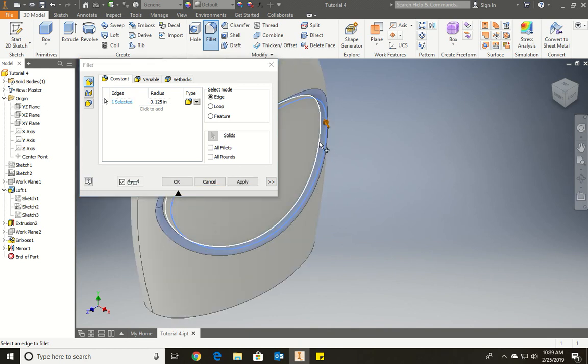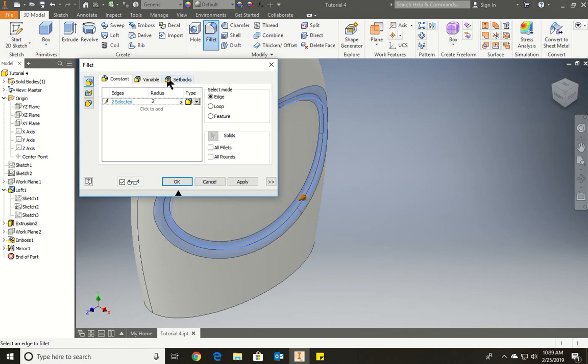And this one here. And we're going to put our radius as 0.2, sorry, 0.2, and then we're going to add again a radius of 0.04. So we have the double fillets. We're going to press OK.